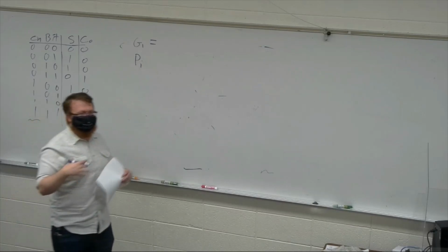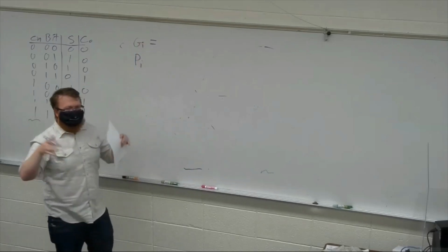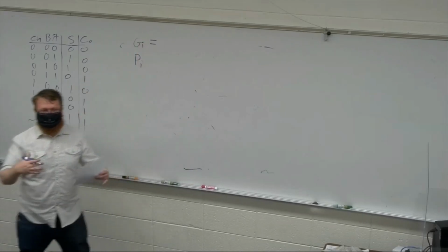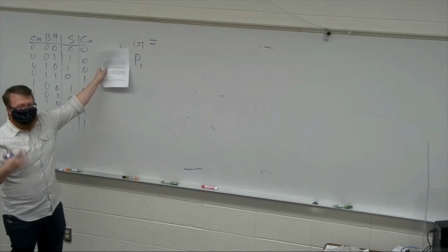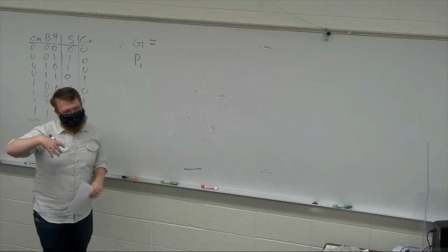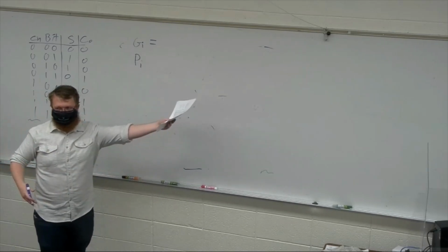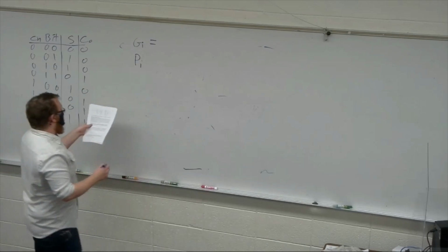So the full adder is saying that for I, this adder I is making by itself a carry. Propagate means that I have a carry coming into me and I'm pushing it out the other side. So it's propagating through the full adder.